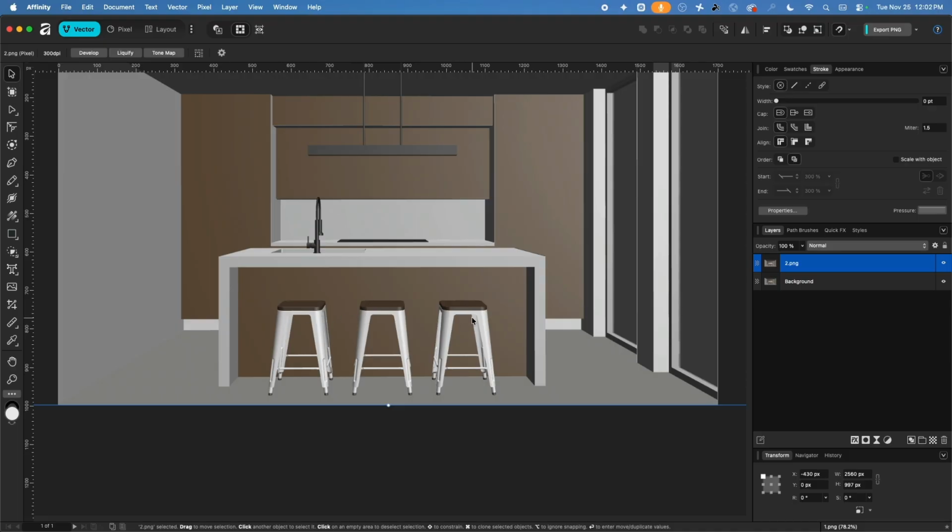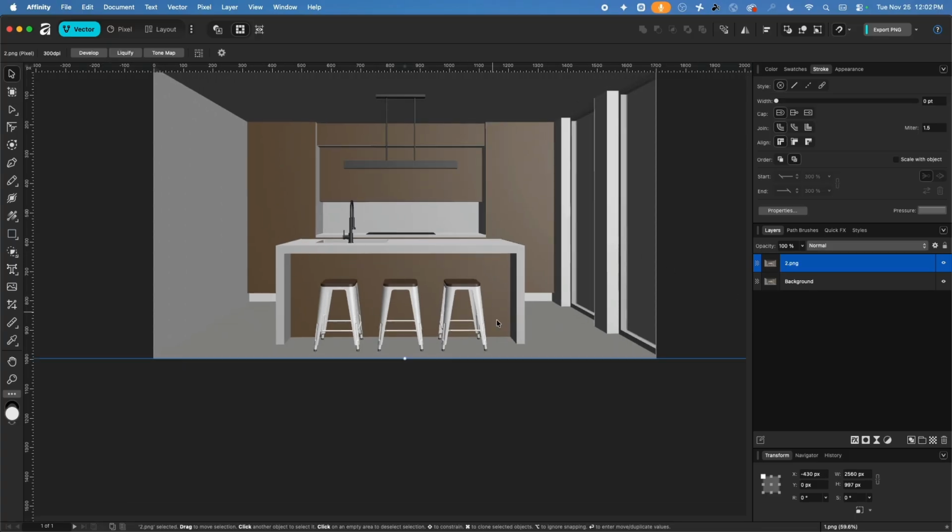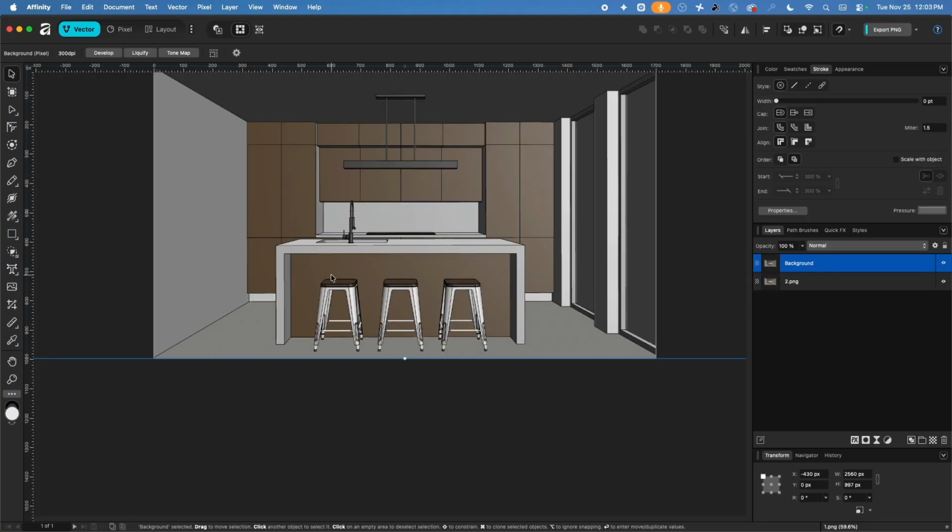Okay. Perfect. So we want to keep the chairs, but not really the rest. We could simply copy this out, but this is destructive. What I would like to do is simply mask everything else. I could also move this one on top and then simply mask out the chairs so I see the chairs below. The way this works is with the layer selected, you just go to masking. And by the way, this is also the same in Photoshop, in any image editing program. We have now the layer with the image and the mask that's masking it.